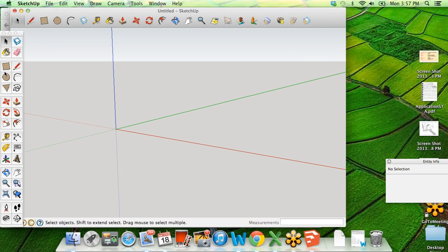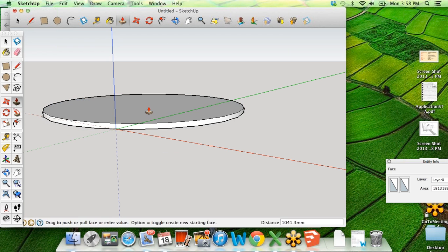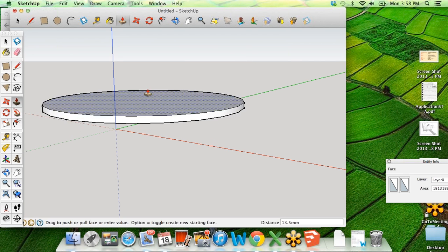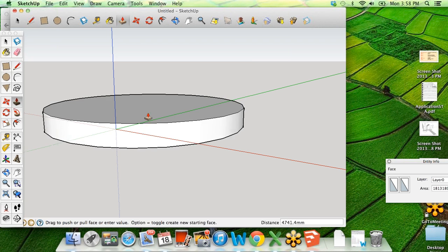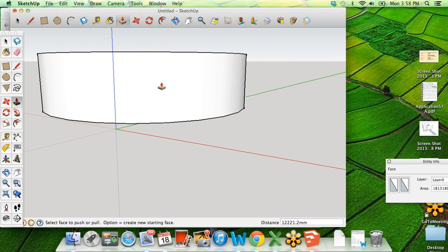Effect. We're going to have the circle. Pull our circle out. And then we're going to press this button, which is called the push-pull button. And when I put my cursor over the circle, you see that those blue dots indicate that the surface is being selected, so the edges aren't being selected, but the surface. And then I can click once and drag my mouse up and down to create either an into or kind of this out surface. I can select again.